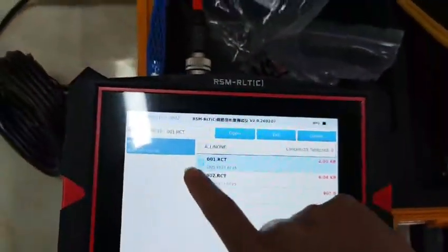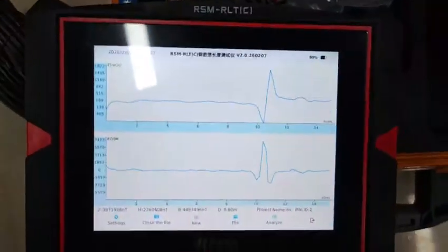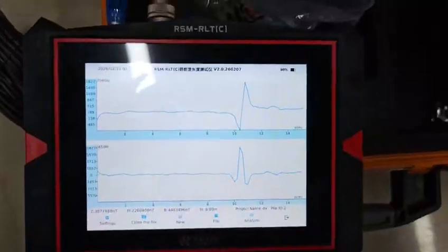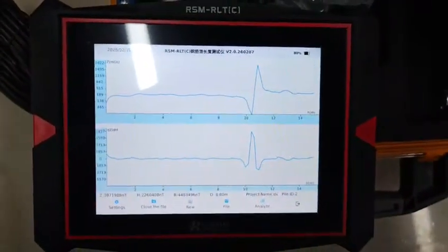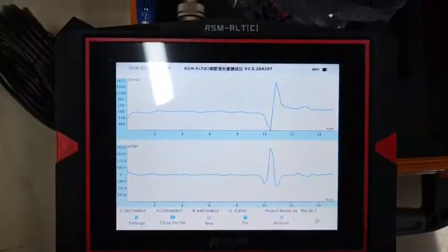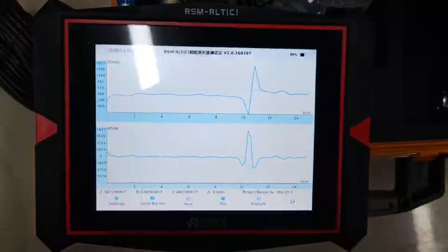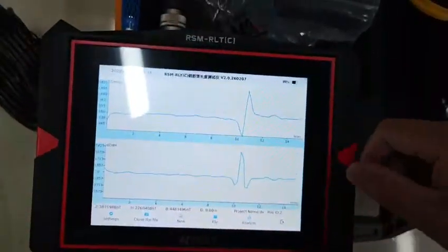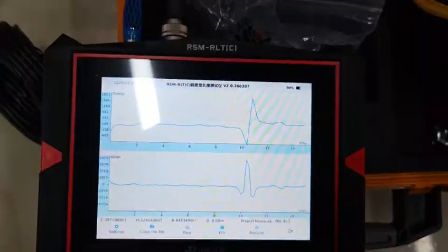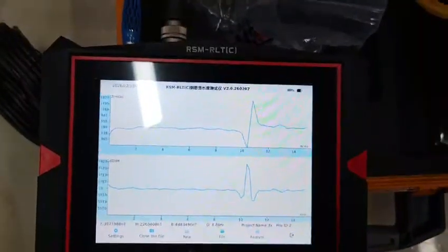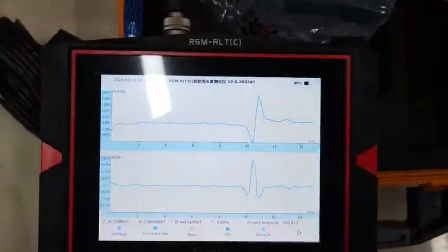And here is the example data. Okay, then we open. In the test, we will bore a hole near the pile, and the hole is always deeper than the pile. So at the interface of the soil and the reinforcement cage, the magnetic value will have an obvious difference.